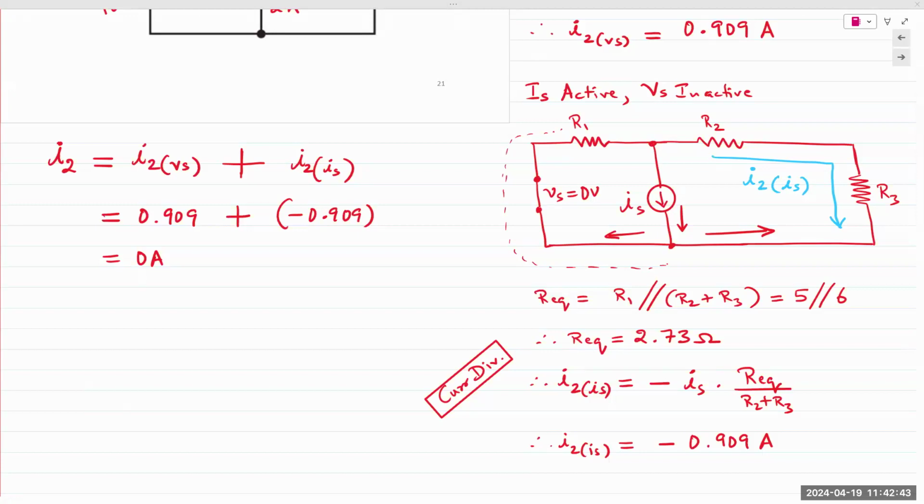Yeah. If this was a physical circuit, all it would mean is that the voltage source Vs and the current source Is are both contributing enough energy that both ends of those terminals, R2 and R3, are at the same exact equivalent potential. It might be 2 volts and 2 volts at both ends, but if it's exact same potential, no current flows through there. In theoretical analysis, we are saying that there's a current coming from the top and a current coming from the bottom, and so they result in 0. That's just theory. Mathematical analysis.